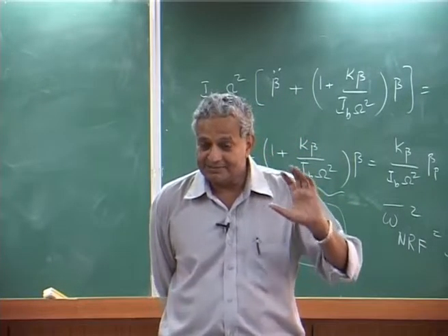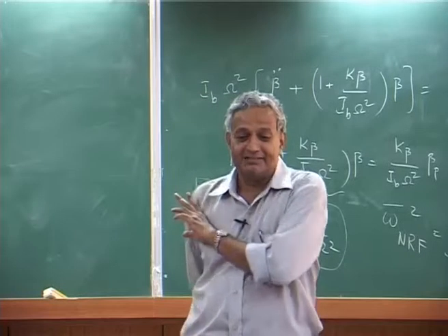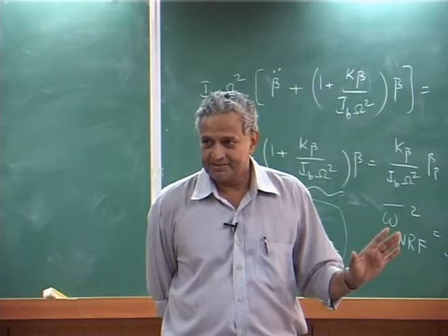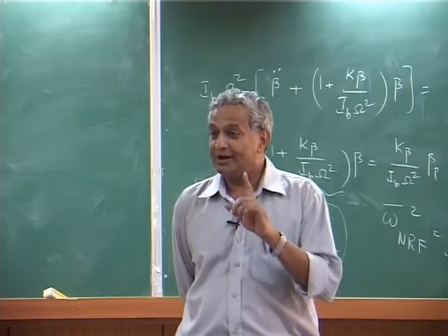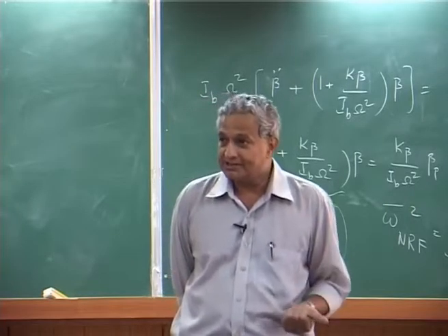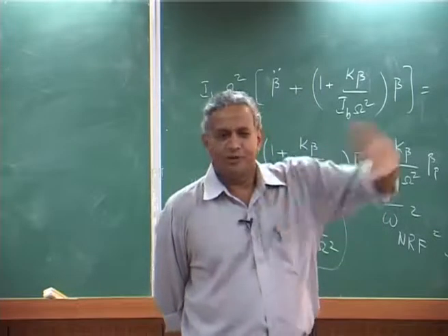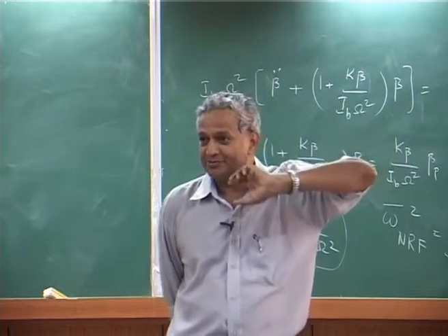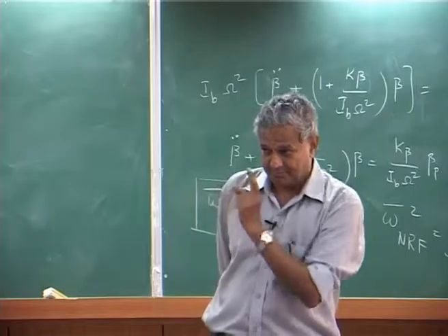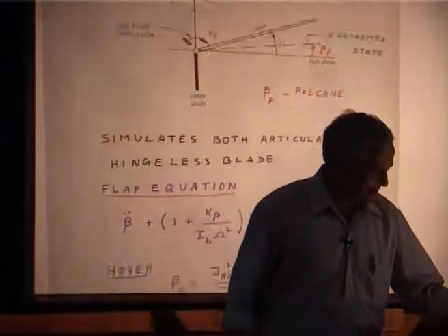Actually, you will find the industry in selecting the rotor system, rotor blade, this is where the major effort goes on. What should be my flap frequency? It is really challenging, because this is going to affect my performance, control characteristics, my loads, hub moment, many quantities. That is why the flap frequency is a very dominant frequency. That is the first flap natural frequency. We will come to that influence part later.